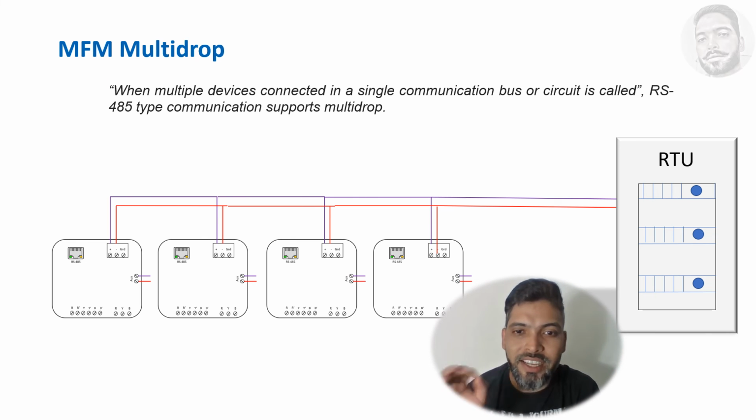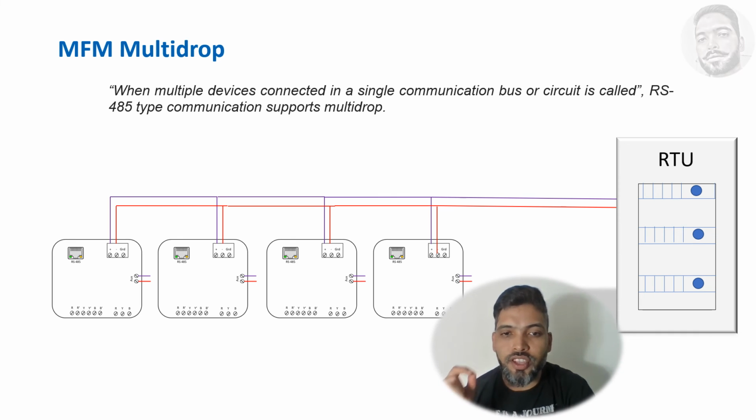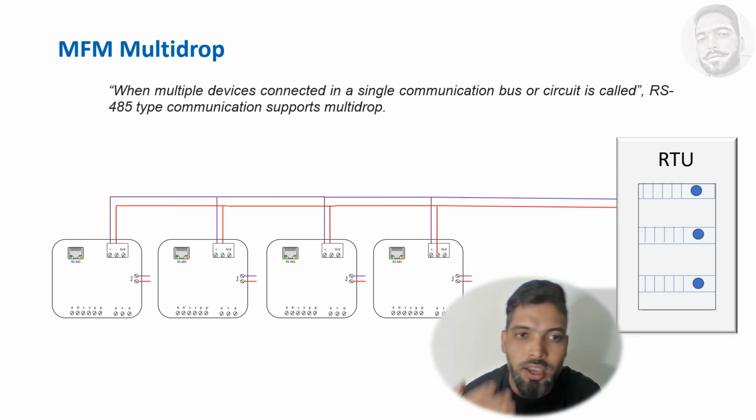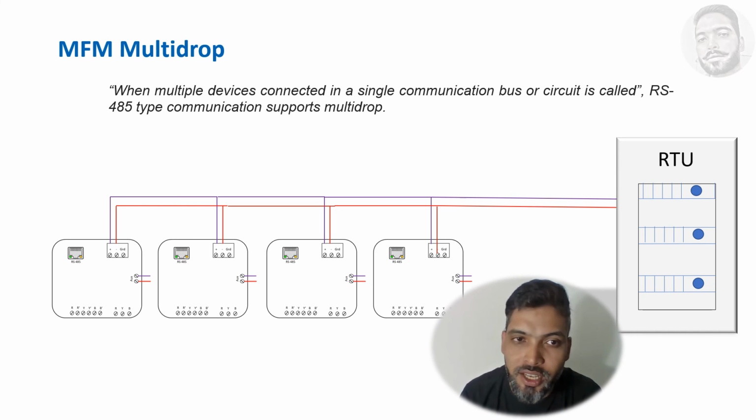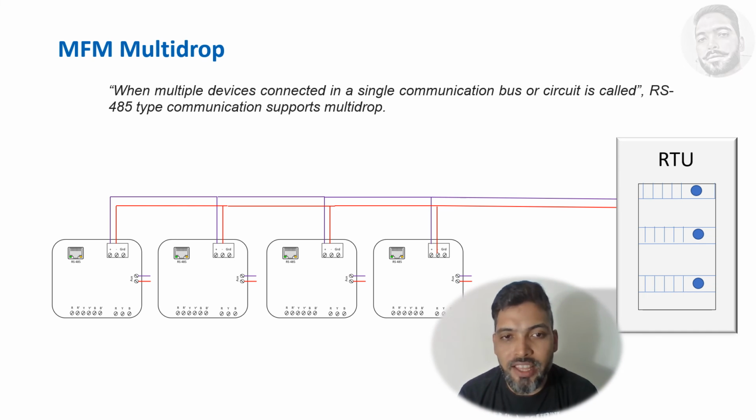So the final tip from my side is, if somebody asks you whether your Modbus is working or not, generally you will have a Moxa cable or something. You have to connect to your laptop and check those signals, and it is a very lengthy process. I have a very small, easy process to check that.